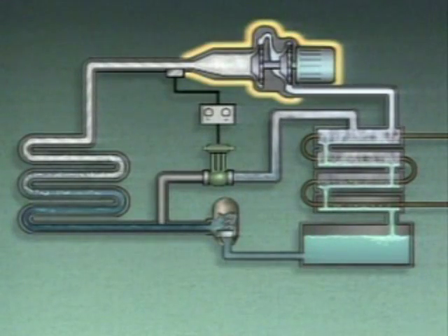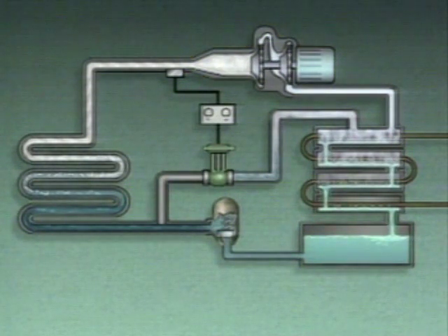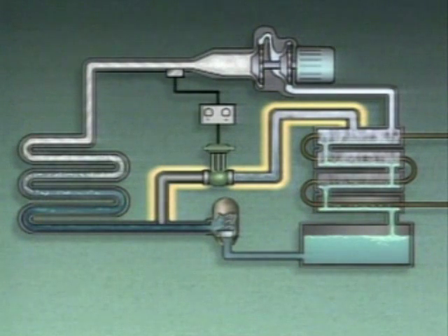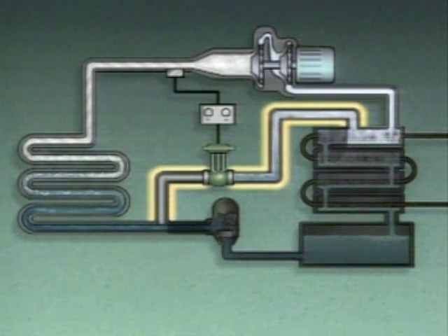In systems with centrifugal compressors, the compressor runs continuously, and there may be additional components to maintain the desired values. For example, in this system, a bypass line routes some of the refrigerant around part of the condenser, the receiver, and the expansion valve. When this is done, the refrigerant that flows into the evaporator is warmer.